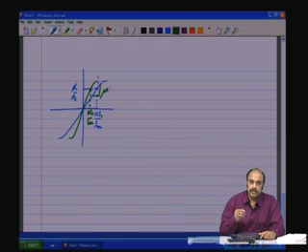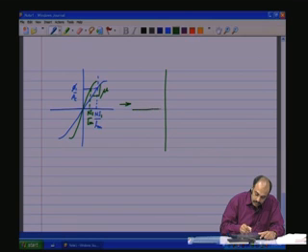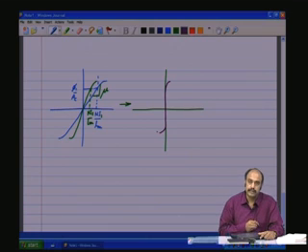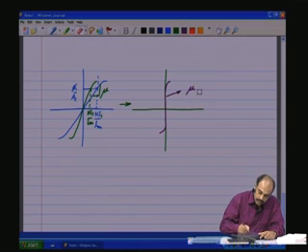The permeability is going towards infinity. So, in the limit, this will tend to this being almost vertical like that. So, which means this has a mu which is tending towards infinity, this being the BH curve.